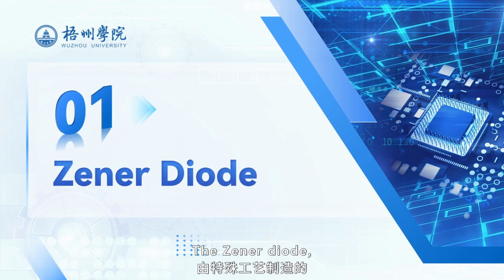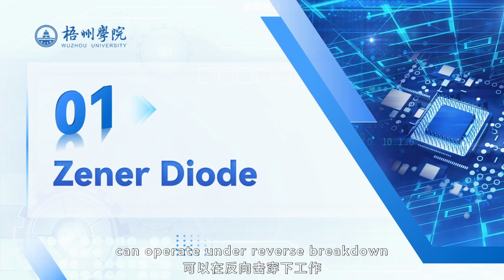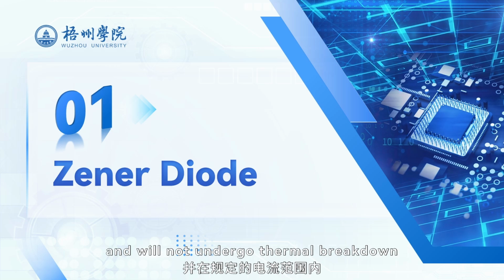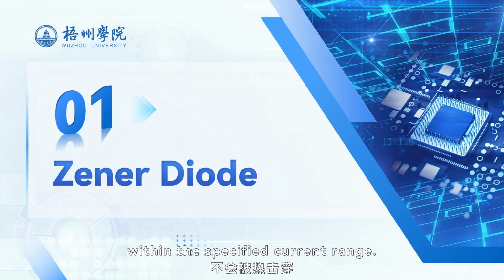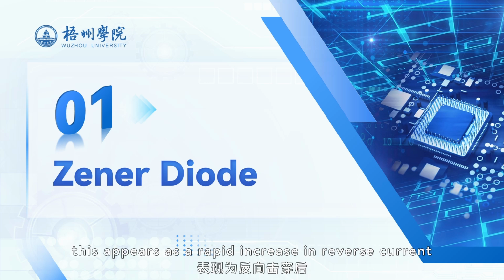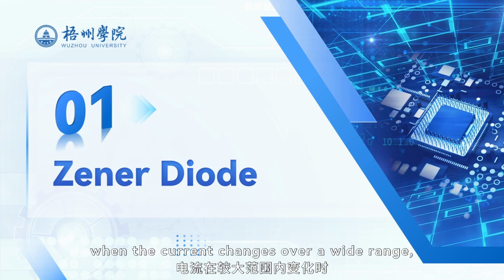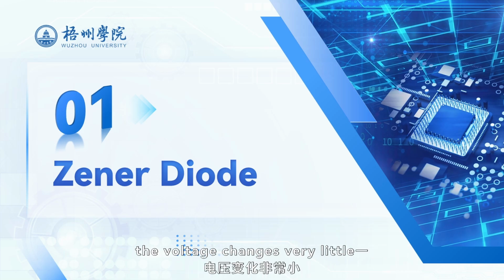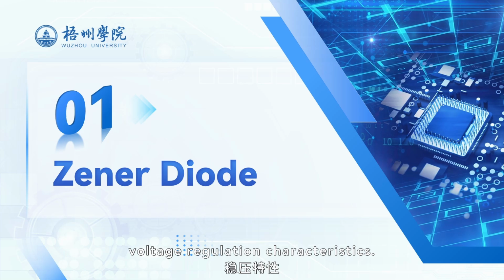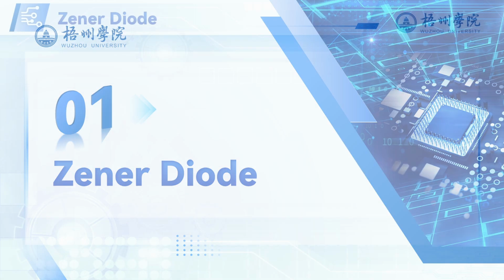The Zener diode, manufactured using special processes, can operate under reverse breakdown and will not undergo thermal breakdown within the specified current range. On the diode characteristic curve, this appears as a rapid increase in reverse current after reverse breakdown, with a very steep curve, indicating that when the current changes over a wide range, the voltage changes very little, showing excellent voltage regulation characteristics. Therefore, the Zener diode is also called a regulator diode.